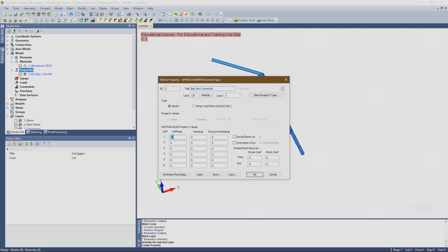First of all, you can represent joint stiffness. This is a whole thing in analysis, representing joint stiffnesses. Pretty much everyone that I know when I worked in industry represented their fasteners using spring dampers in FEMAP, and there are templates to understand the joint stiffness.